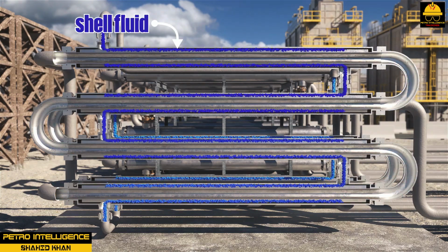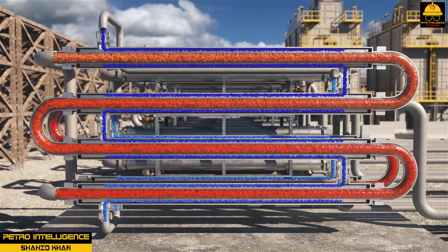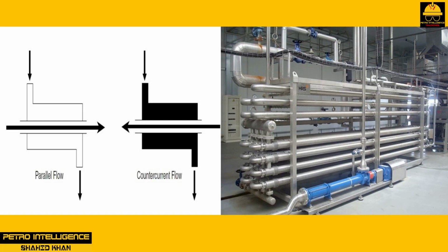In a countercurrent flow exchanger, the exit temperature of one fluid can approach the inlet temperature of the other fluid. Less heat will be transferred in a parallel flow exchanger because of this reduction in temperature difference.